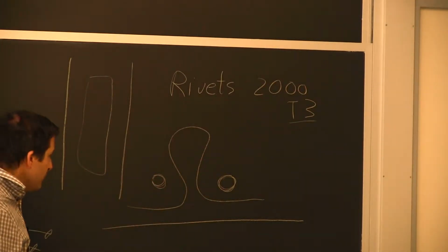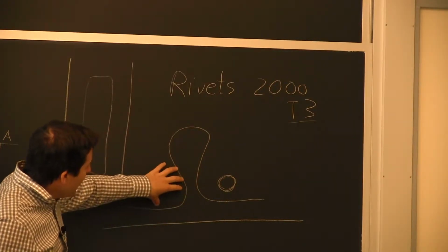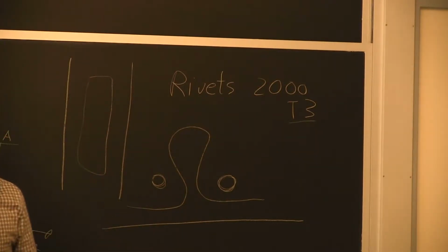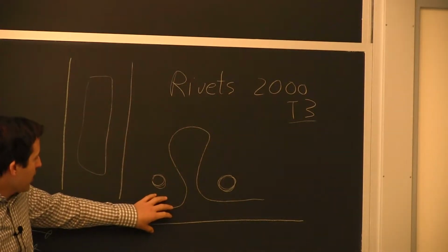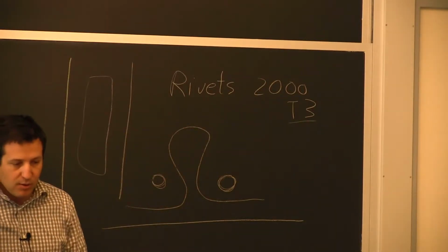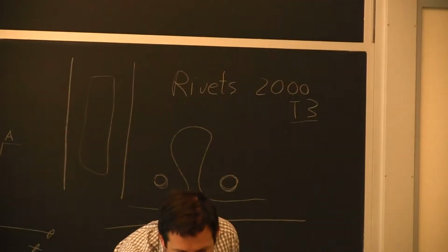I'm mentioning it because that's where you really gain more in terms of your yield strain, and you also gain a lot of strain hardening. So how much the flow stress is going to increase in plasticity. Well, your stress strain curve here is going to be going way higher, and if you keep going, when we have these curves, if you're looking at this graph here, it's the hardness over time.